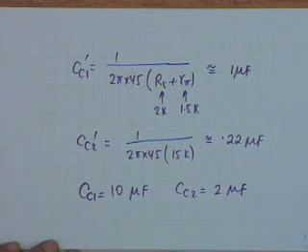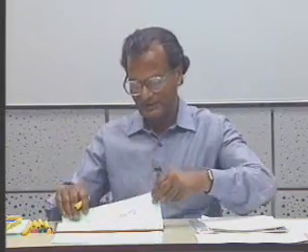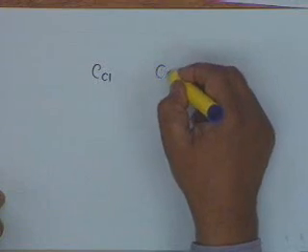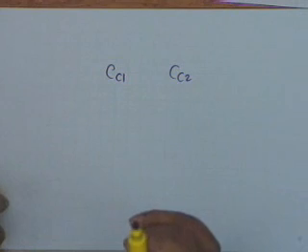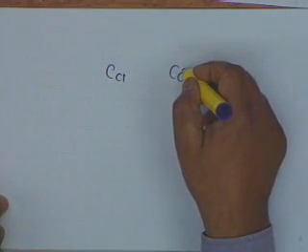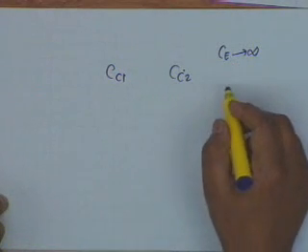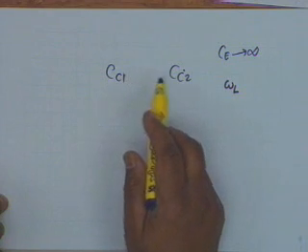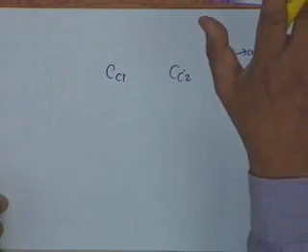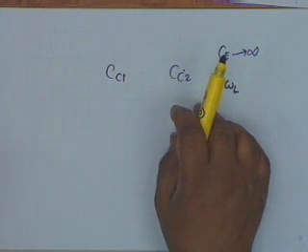But we said that we will use the larger of the two as such and the second one larger of the two. No, here the situation is slightly different. Here the situation is 3 capacitors. We have already chosen CE, that is the largest value, 50 microfarad. Larger of the two is when CE is assumed to be infinity. Let me recollect what I said. If your choice is to determine omega L by either CC1 or CC2, assuming CE to go to infinity, CE is 1000 microfarad, you have already done that. Then you calculate from the specified omega L, you calculate CC1 and CC2, have the larger of the two as the value that is calculated, the smaller one you multiply 5 times.